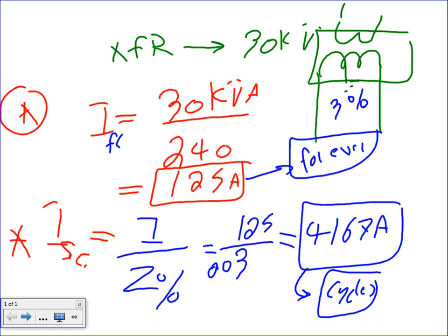When we study circuit breakers, there are 2 types. A circuit breaker will see this huge amount of current going through it. If it's an electromagnetic circuit breaker, it creates a magnetic field because the current is so huge, and that magnetic field will pull 2 contacts open. That's most of them. If it's an electronic circuit breaker, they send a signal, like a relay, to a coil, energize that coil, and the coil physically opens these contacts to interrupt the circuit.